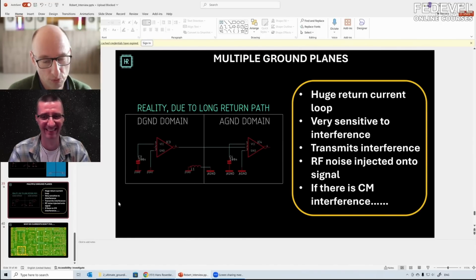For instance, if you make a power amplifier, then you can imagine that the output stage runs very, very high currents. And even through a plane, that will cause very tiny voltages. Now, if that amplifier has a distortion of minus 110 decibel, that means that the signal on your ground has to be 110 decibels lower than the signal that comes out of your amplifier. Now, that's a hell of a lot. I mean, that's 300,000, I think. So there you actually have to be careful.